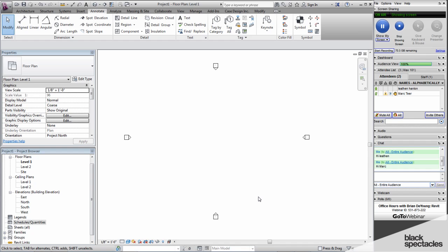Yeah, yeah. I mean, particularly if it's a regular building where the floor plates and the column positions and all of that are in the same location from floor to floor, you can do all kinds of things. You can put them into a group, and then you just have to edit the group, and then all the floors update. The problem that we run into on the projects that I work on is that we have columns that are changing in shape and size, and they're not vertical, they're leaning in one direction or multiple directions. And so primarily for that reason, our structural engineers, and for analysis purposes, they model all their columns from floor